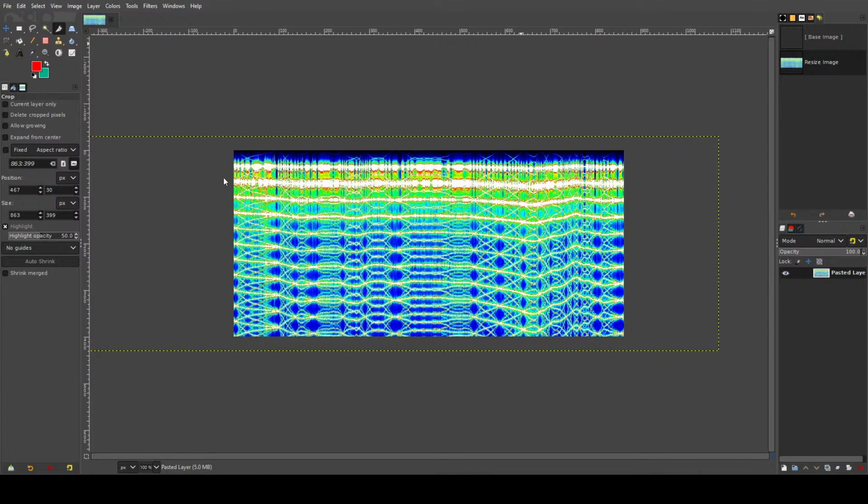So we go to export as, we choose TIFF as file type. And then when we hit export, it will pop up a dialog. And now let me check which one it is. Okay, so we want to have TIFF with the following settings. Image compression, none. Pixel order, interleaved. And byte order, IBM PC.